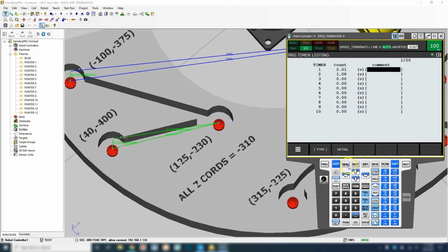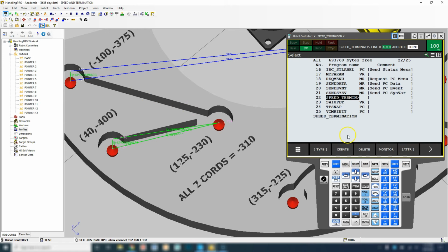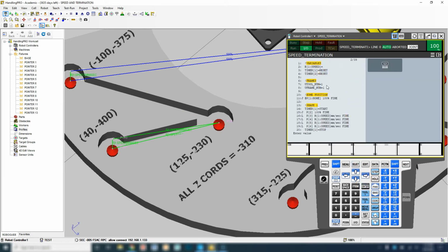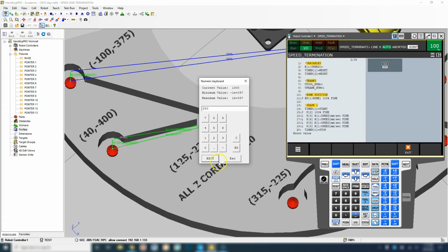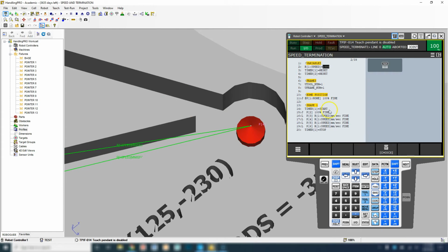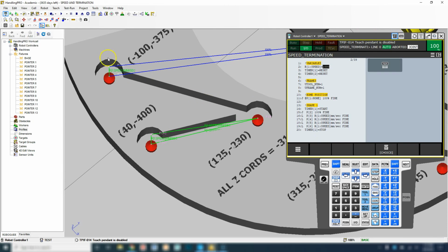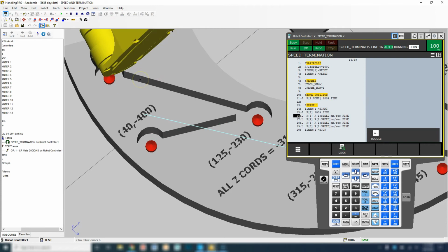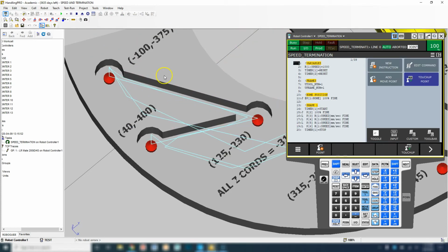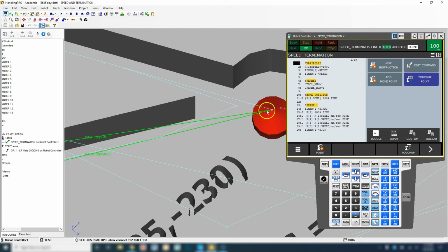So if I go up to my program again, and I go from 1000 to say 250 millimeters per second and run this, you'll notice that that arc, even though I didn't change anything down here, gets closer to this point right here because the robot is not going as fast. So let's run this and see what I mean. There we go. And notice how it got even closer to that point.